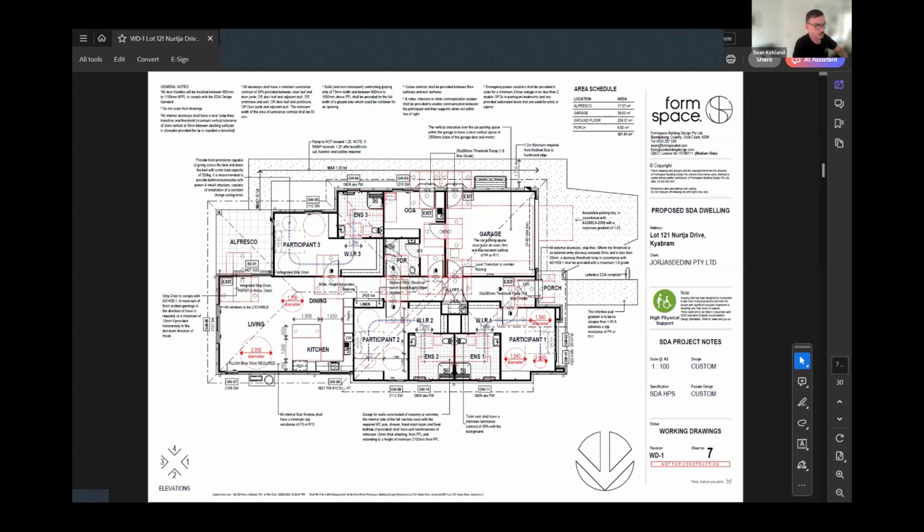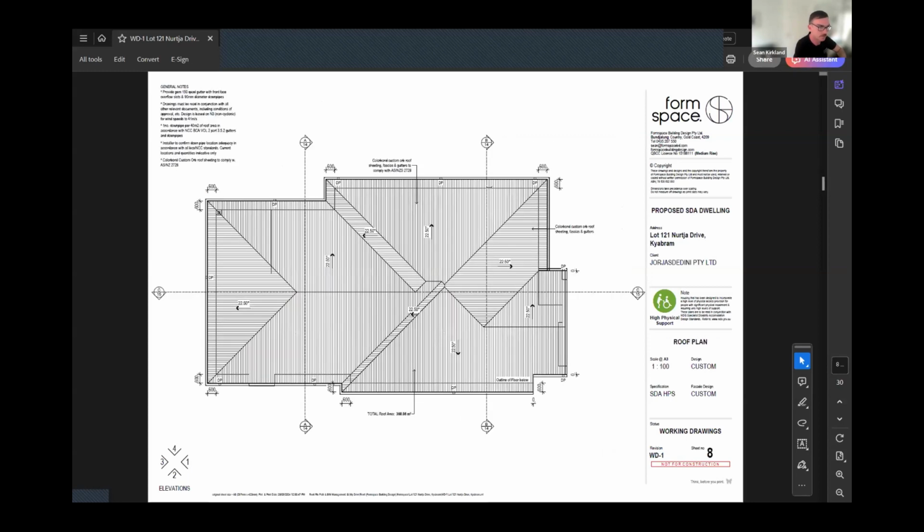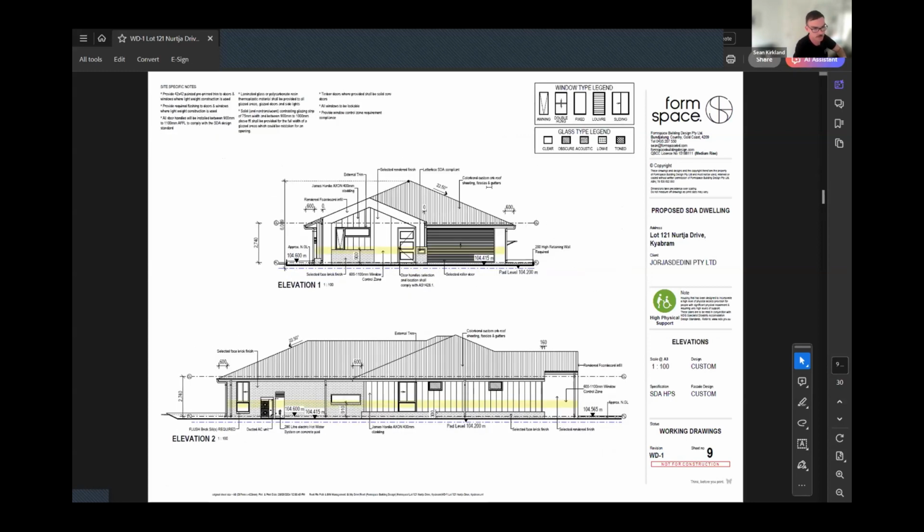This affects a whole host of things in terms of buildability, which means there's consideration required in terms of perimeter hobs to allow, I guess, concrete paths to abut correctly for the DPC and termite inspection. And a lot of these considerations aren't at the forefront of the designer's mind unless they're skilled or understand this when they're designing these spaces.